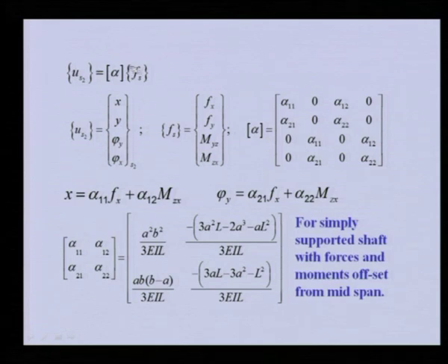So, we are using those equations directly here. You can see these are the shaft displacements, corresponding to when we consider the bearing as rigid and the shaft as flexible. So, these are the reactions at the disc location, and these are the influence coefficients which relate these two quantities.